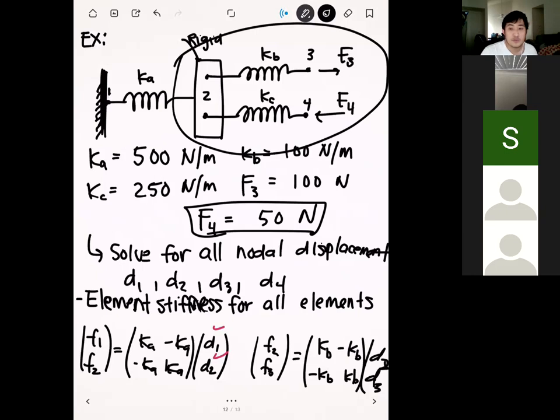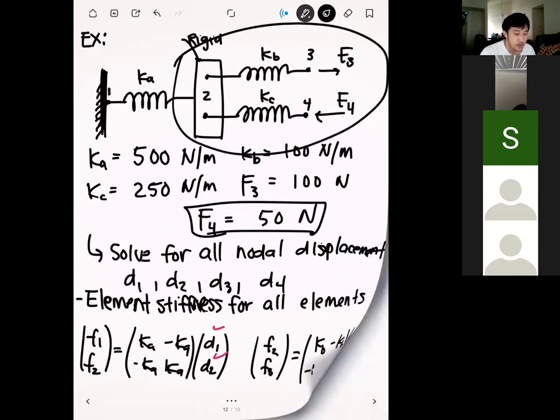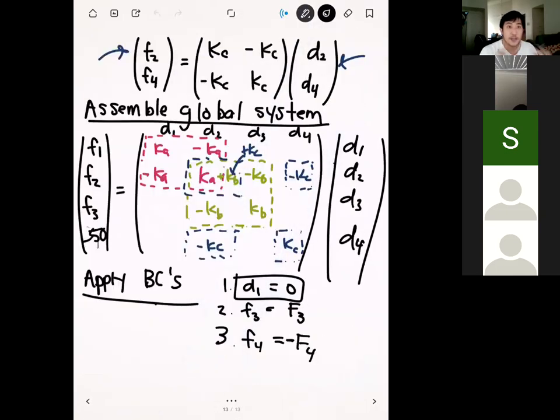Another question, Professor. Sure. What's up? So these are only for the external forces, right? We cannot do these calculations with internal forces, right? Yeah. So there will be internal forces that develop from this, but those don't make it into the system because we only factor in things that can basically affect change in the system. For the finite element system, we're only interested in things that can cause a displacement, and that's only going to come from external forces.